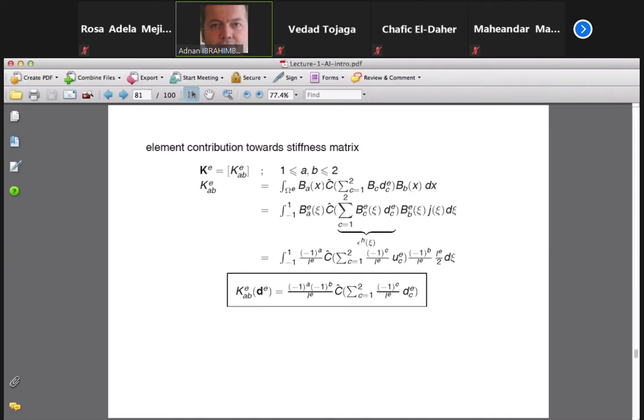Recall, this is like a linear expression when you have just Young's modulus E instead of the C. Now, in nonlinear analysis, you have to compute the current value of strain, which you do by using the product of the B operator, which is dN_A/dx, times the nodal value. So this gives you the current value of strain for the tangent modulus. And then you basically multiply this by either B_A and B_B, and hence you obtain your tangent stiffness. Another one becomes like C over L.